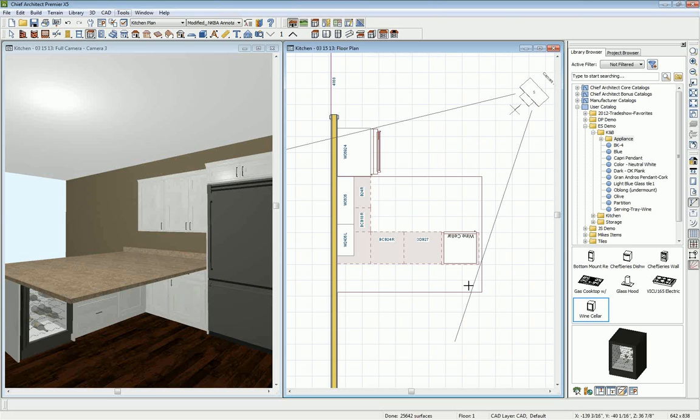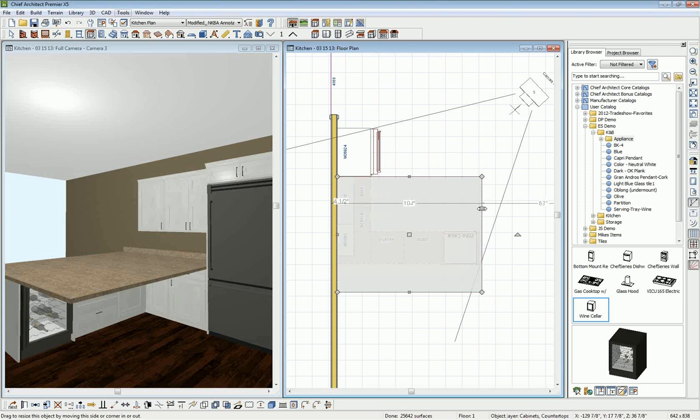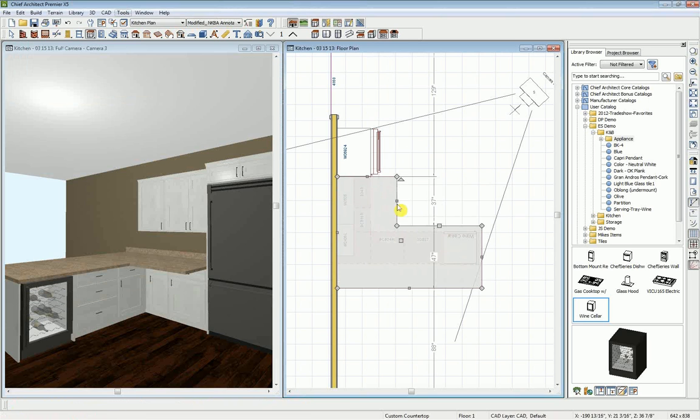So we have this nice big slab down. I'm going to select our edge, and that is actually exactly where I want it. So now let's select the other edge, and this needs to be 84. So we'll single click on our temporary dimension to 84, hit enter. And now we need to use our break line tool, and that's in the bottom editing toolbar. So with that break line tool, we can just put a break in there, drag that down, and then from